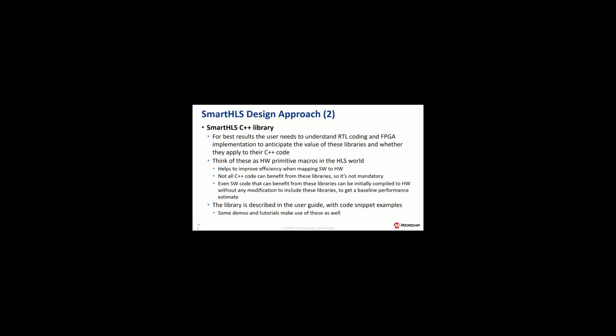Which is the hardware bit. It's best if the person writing C++ understands RTL and understands FPGAs, but they might not. As long as somebody in that loop can cast an eye over it and make a call on it, which is the whole point. Somebody can write the C++, test it, run it through, know it's good, then you look at it from an optimization perspective. That helps. You might get a better output.